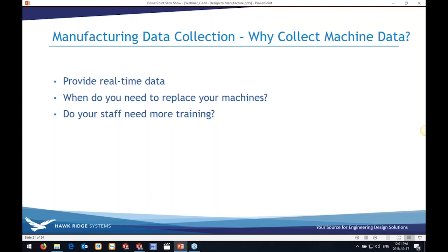But tying into that in Industry 4.0, Hawkridge decided to partner with Predator CNC software. And a few of the functions are DNC, so you can actually communicate to the machine. You no longer have a guy running with a USB stick across the shop floor. You can actually set up all the machines wired or wireless and just send the files or call the programs from the CNC.